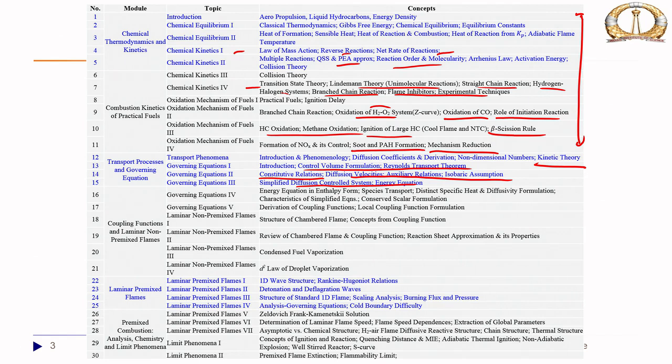We derived the species transport equations, and we incorporated the different ways by which we could simplify these reaction systems, simplify these governing equations by invoking distinct specific heat and diffusivity formulations, okay. And this led to simplified equations, but then after we arrived at the simplified equations, we realized that this nonlinear reaction rate term creates a very big problem.